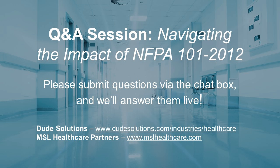Well, first of all, the new fire door inspection that's required requires a trained individual with documentation of training, and is looking at a plethora of items that must be inspected. I never knew there were so many things on a fire door for a person to inspect, but talking with some of the companies that do this for a living, they claim it takes between 15 and 20 minutes per fire door to do the inspection. So it's more than just making sure the door closes and latches, and the proper clearances, which is what we typically check during that building maintenance program. So no, we need to do a little bit more than that.